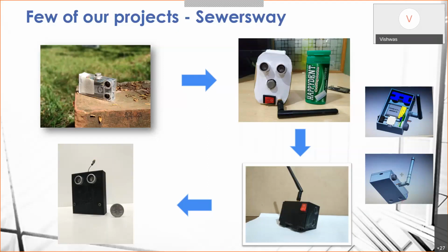So we are using LoRa for the communication from the manhole. The whole device fits inside the manhole; the manhole cover will contain this device. It continuously measures the water level inside the manhole and sends the information to the nearest LoRa gateway. Through the LoRa gateway, we send it to the cloud.